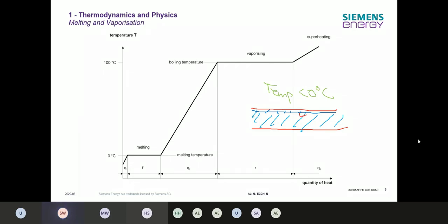So the avoidance is that we have some heating over here. That's normally some electrical wire where we're sending electricity through. So it's a trace heating, and the trace heating is switched on, making sure that you get a certain temperature inside the piping so that the water will not freeze. So that's why, over here, melting just needs small energy, melting temperatures, getting into here.